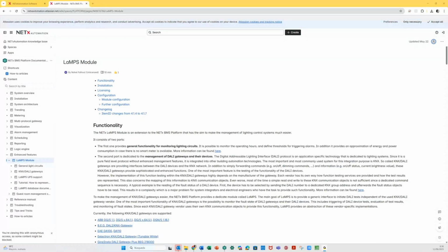This is one first comment from my side. But it's very important to understand that DALI technology, even in the past, has a very interesting second approach, not only for controlling lights, but also for the supervision of these devices. One of the most important things we are facing with the BMS is not only integration, but also supervision of everything that is inside our installations, because this is important for your end customer, and of course we have to be ready to offer this kind of functionality. So supervision of the lamps, of the ballast, any failure has to be registered.